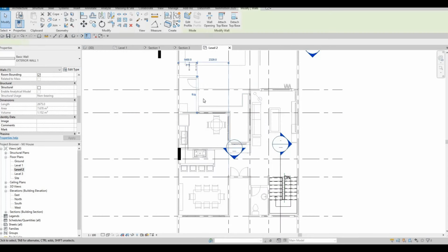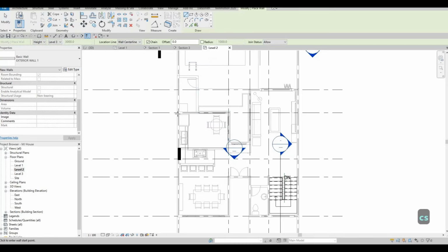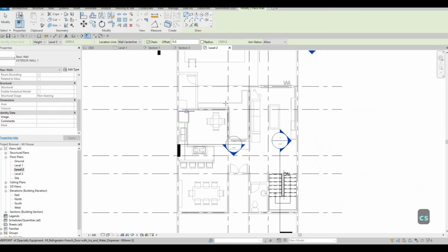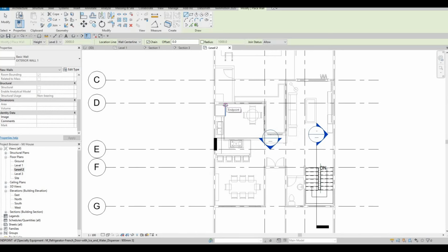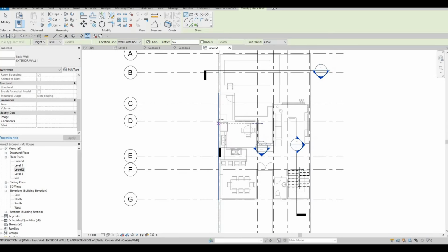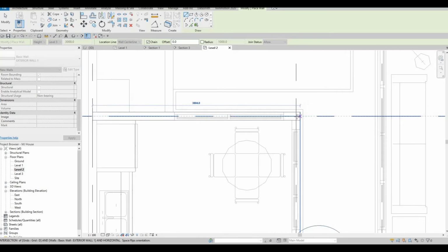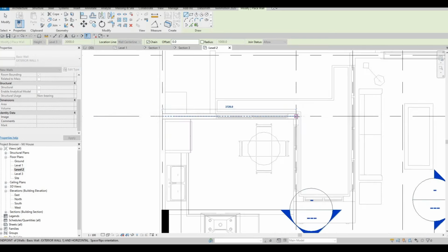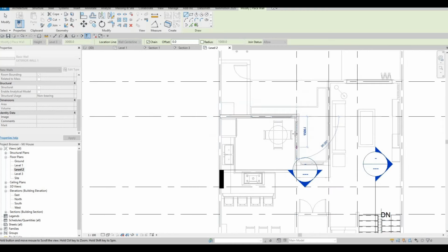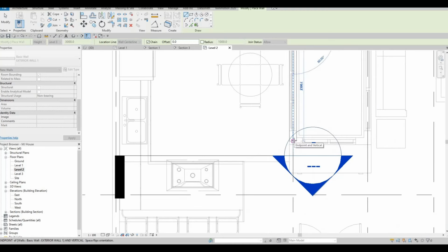I'm gonna select this wall because I know this is an exterior wall right here. But once I type in CS, that's to create similar, I'll be able to add it instantly right here. So I'm gonna type in CS and I'm going to add it. We're gonna start off by adding D1 right here, going across. So we're just gonna copy the one below, going across D2, and then going down right here, just copy it.